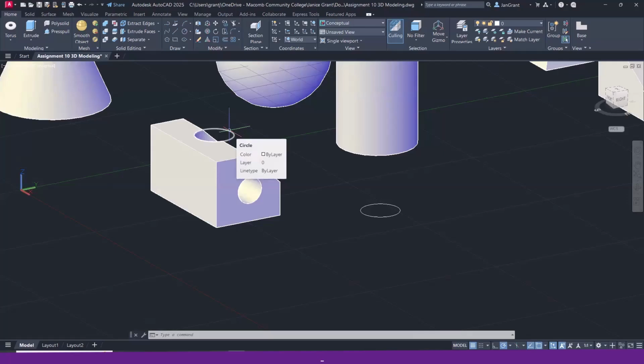geometry does stay. When we use extrude, which is very similar, it's going to take away and delete the 2D geometry. The reason for knowing this is that you may be working with a 3D solid that has 2D geometry and you're trying to figure out why it's not working. Well, you might be clicking on the 2D geometry instead of the solid model. So sometimes I'll just go in here and delete some of the 2D geometry. Like this one's obvious. You can just click on it and pick Erase.